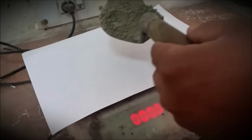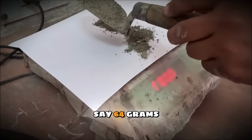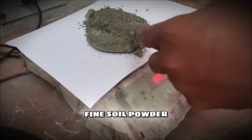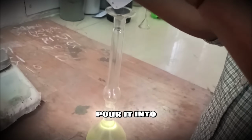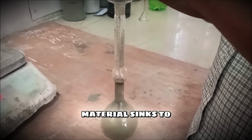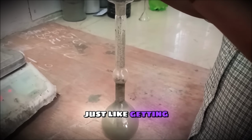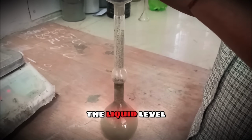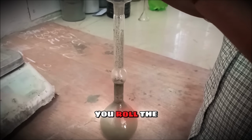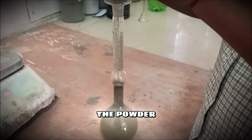Step 2. You take a known exact weight of your dry test material, say 64 grams of cement or fine soil powder. You very carefully pour it into the flask. Step 3. As the solid material sinks to the bottom of the bulb, it displaces the kerosene. Just like getting into a bathtub, the liquid level rises up the narrow neck. You roll the flask gently to make sure absolutely no air bubbles are trapped in the powder.